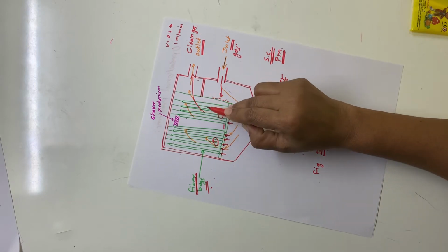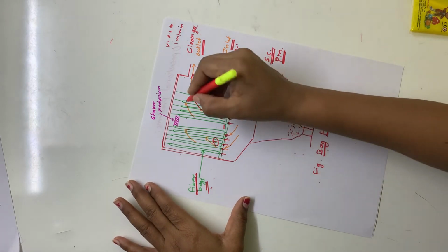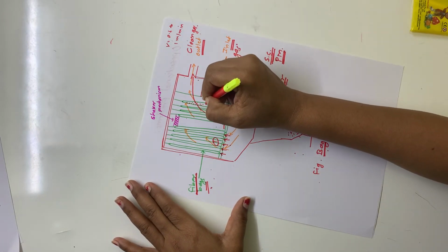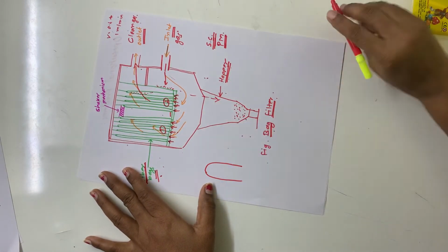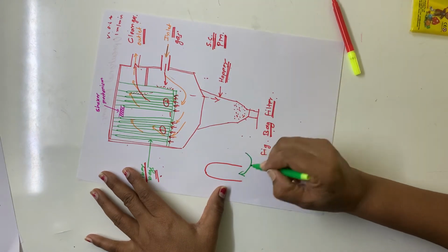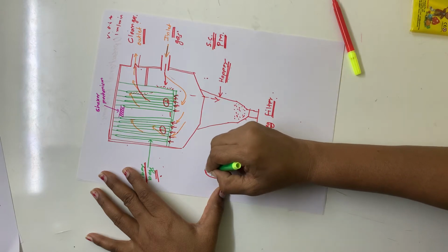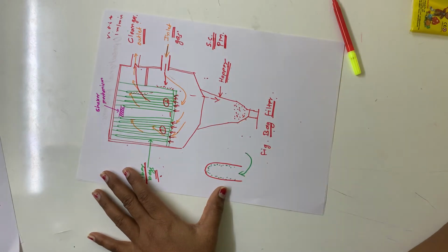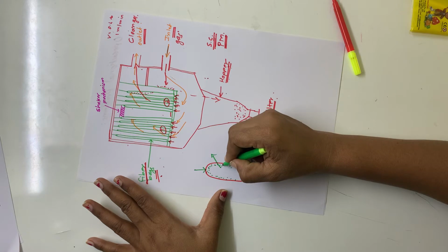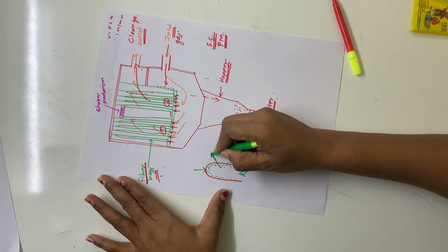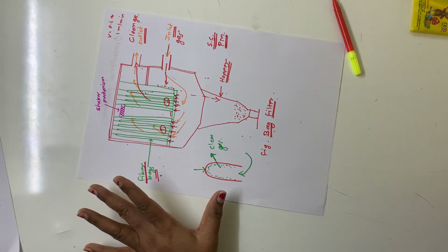Because the bag is fabric and mesh-like in nature, the particulates attach to the inner side of the bags. I will show you a bag here. When gas comes this way, the particulate matter starts attaching to the inner wall of the fabric bag, and the clean gas automatically goes out through the porous nature of the bag. That is the clean gas. This is how it functions.